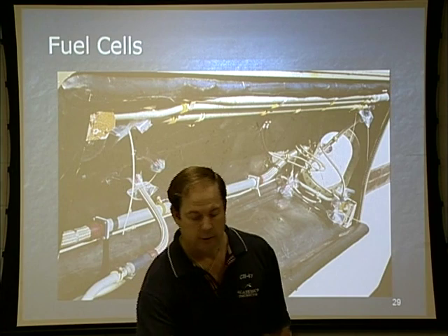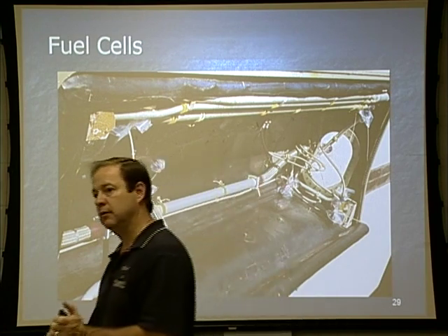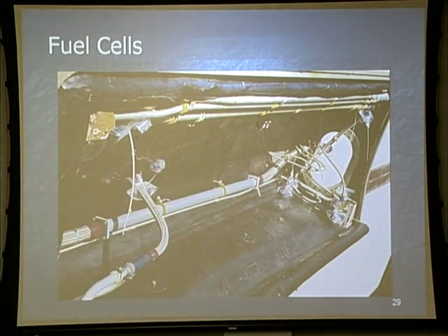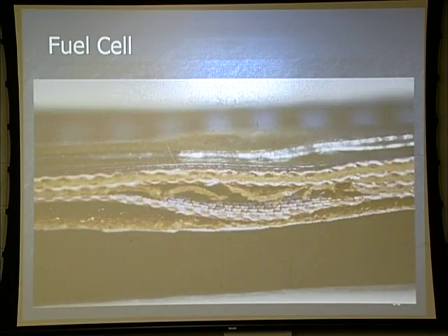Two, if those tanks bend or crack, this bladder is made to just fold up on itself or indent to absorb the deformities of the aircraft in its crash sequence. Any questions about that? That's the benefit of the bladder. Now we're going to go more into the bladder here, because we're going to actually tell you that this bladder system will withstand up to a 50 cal round.